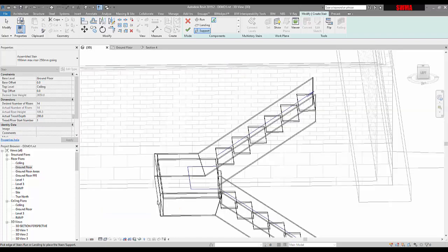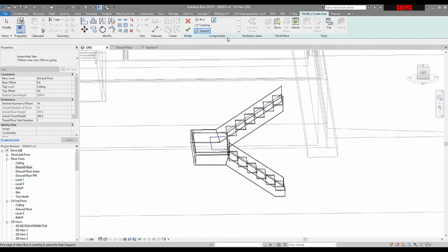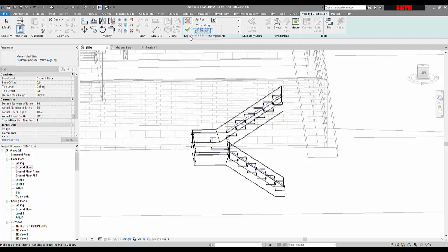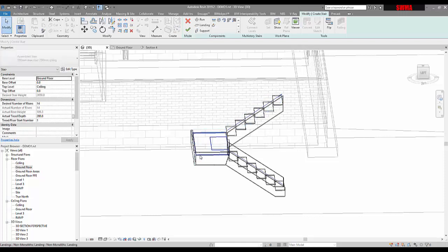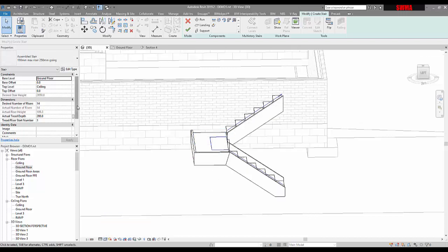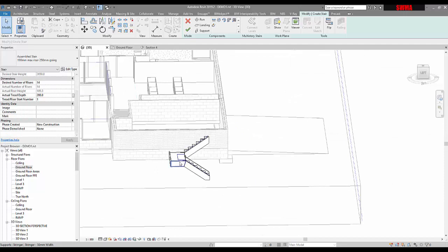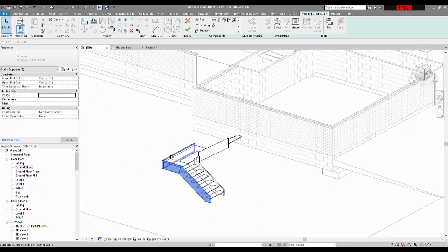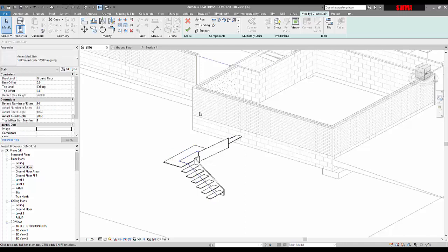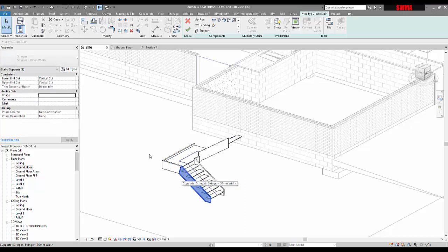Let's go wireframe. I think it's gone and added a support. So let me just escape out of that and just show you what that means. It's a hidden line, turn, and then with nothing selected, just get rid of that, get rid of that, get rid of that. It's already got stringers in here for support, so now when I go and add a support, now that's working. And these supports could become other items.